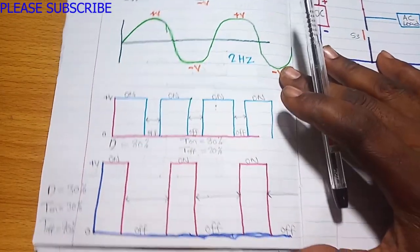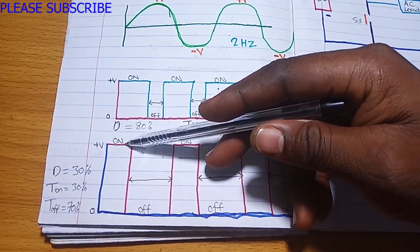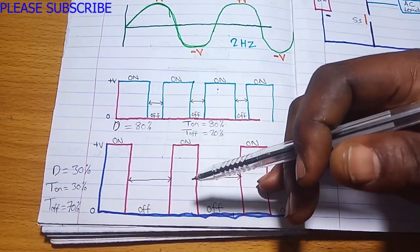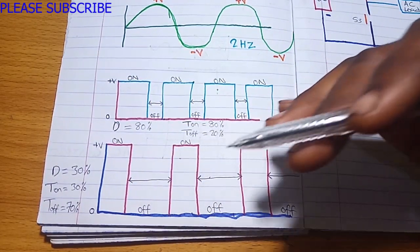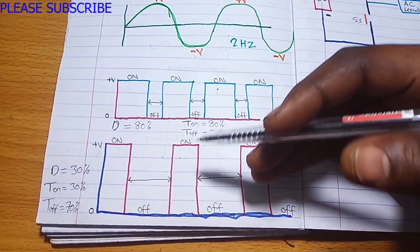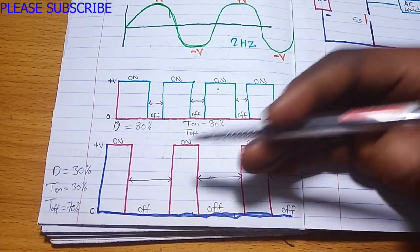So let's look at another signal. Once we decrease the duty cycle, this is a 30% duty cycle. The on time is 30% on, while the off time is 70% off. This also affects the voltage that an inverter produces. The output voltage also depends on the duty cycle. Once the duty cycle is high, the output voltage is increased, and once the duty cycle is decreased, the output voltage is also decreased. So that is where the duty cycle comes in an inverter.